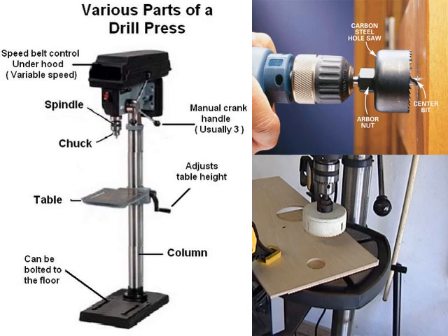Or it could be a way to make a wooden gear: you can start with the circle and then measure out where your gear teeth need to be exactly, and you can get templates for that on the internet. But you can start with the circle and then cut out the teeth from that with a jigsaw.